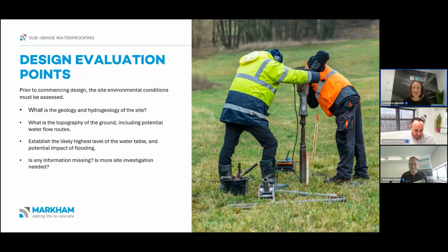So again, I feel like we're hammering this one hard, but the intent of BS 8102 is for the waterproofing strategy to be established extremely early, right before we're commencing design. You'd all be familiar with doing site assessments. What's the geology? What's the hydrogeology?